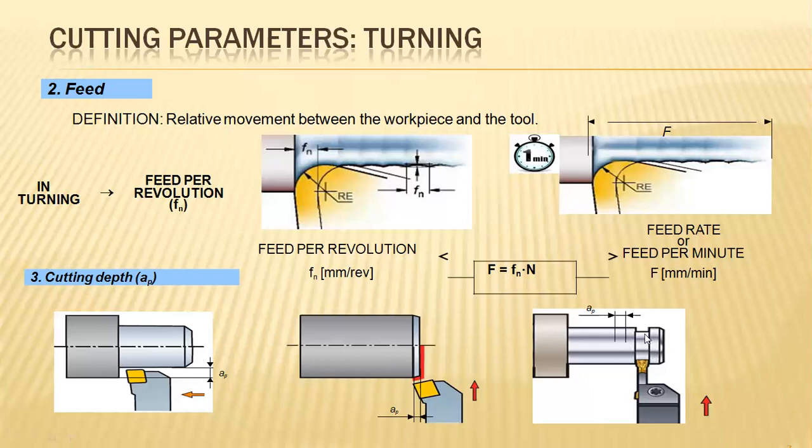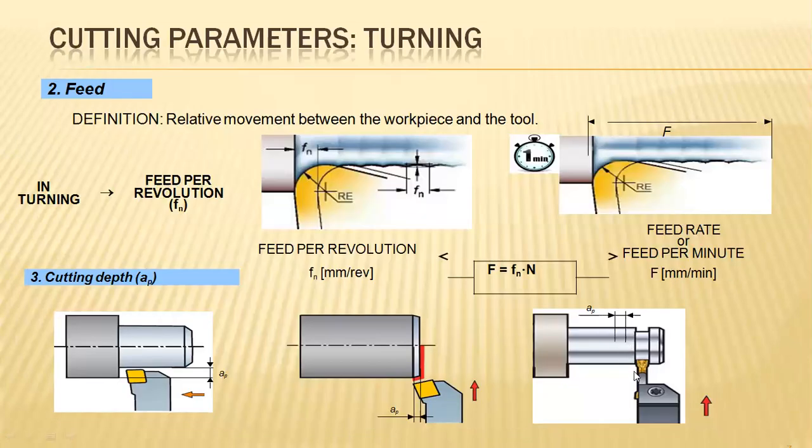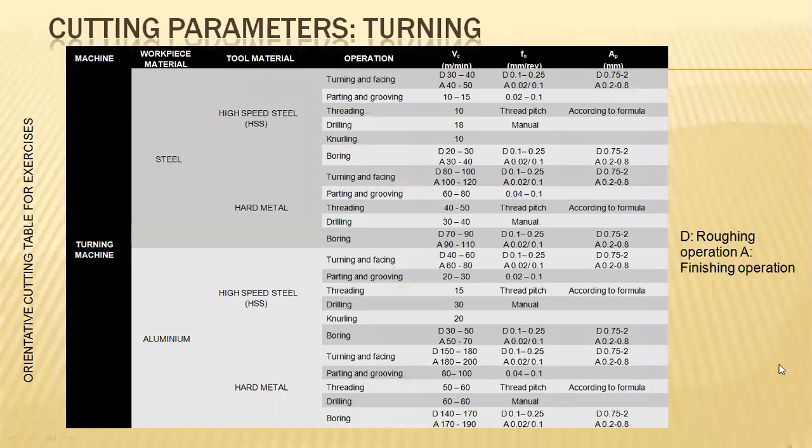See here, we need to consider the slot and facing operations; after being faced, here is the step condition. This is the initial step. Secondly, the facing operations, and thirdly, the slotting operations, only removing the material other than the diameter to a particular extent.